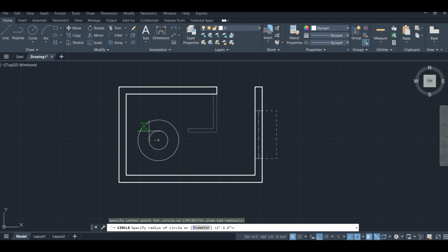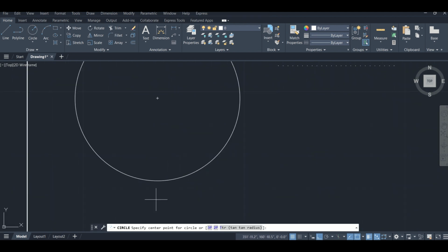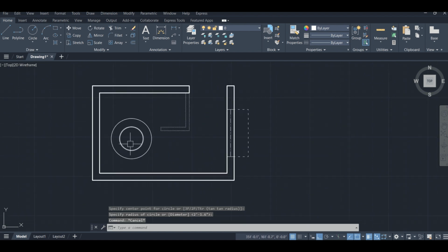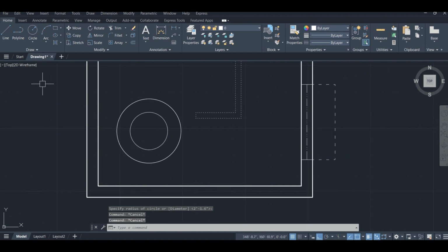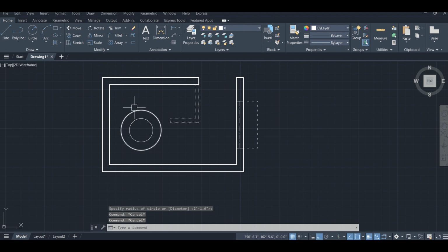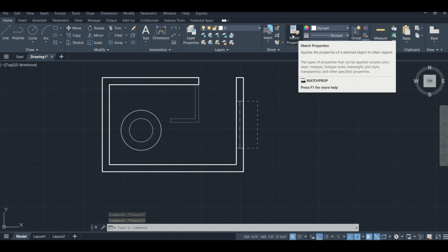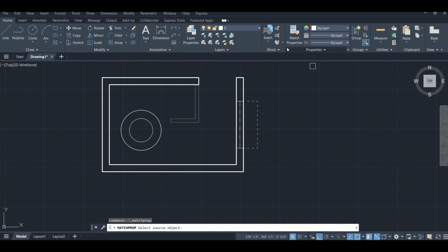giving to this one like a random object, right? Nothing as per the drawing. So here is something around object, but I don't want to go with the tedious process that I have to select from the line from here, then I have to set the scale. So once you have set the scale and the type of line, the change the property of line, what you need to do, there is an option match properties. So click this one.